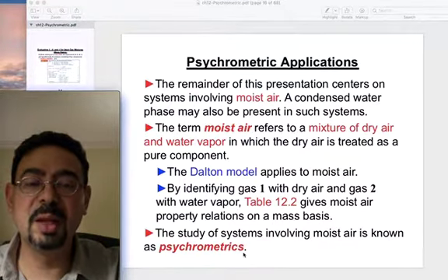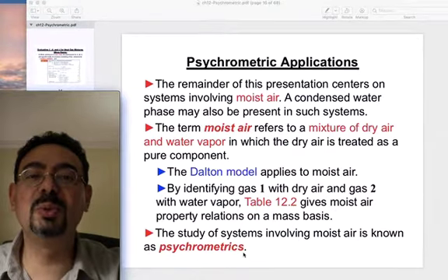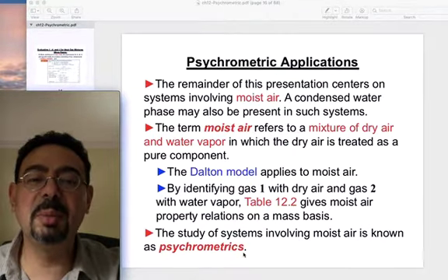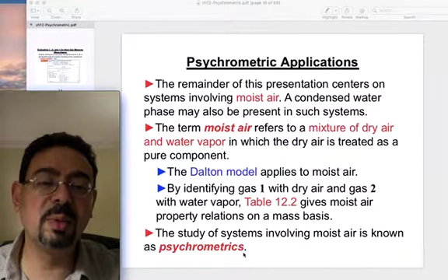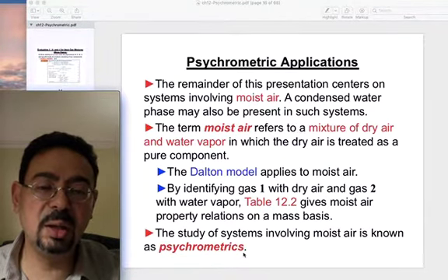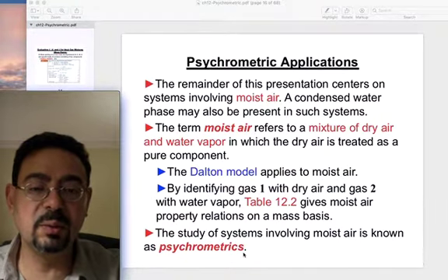All right? So they have the same temperature, but they could have two different pressures depending on how many moles are in that room. Partial pressure will end up being the mole fraction multiplied by the total mixture pressure, right? So let's go to chapter 12 and see what else he offered to give us.